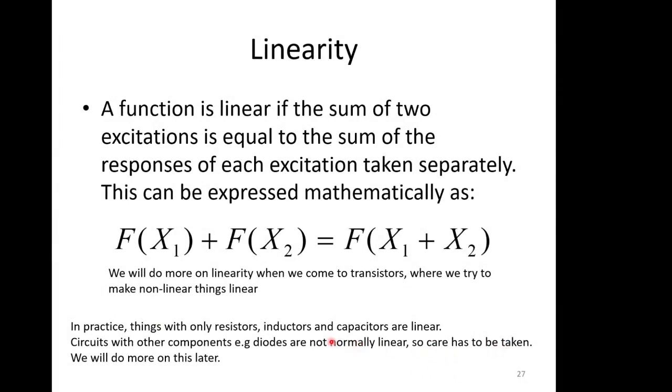But engineers spend an awful lot of their time trying to turn non-linear circuits with diodes and things into linear ones, so they can apply basically all the network theory we're going to learn. Because if you can't apply the network theory to a problem, then the problem becomes quite hard to solve. So we will try and massage circuits to be linear. It may be that they're only linear over small ranges of operation, so we have to constrain them. But engineers spend a lot of time trying to make things linear, because it makes your life much, much easier. So understand what linearity is, because it really makes life easy going forward.